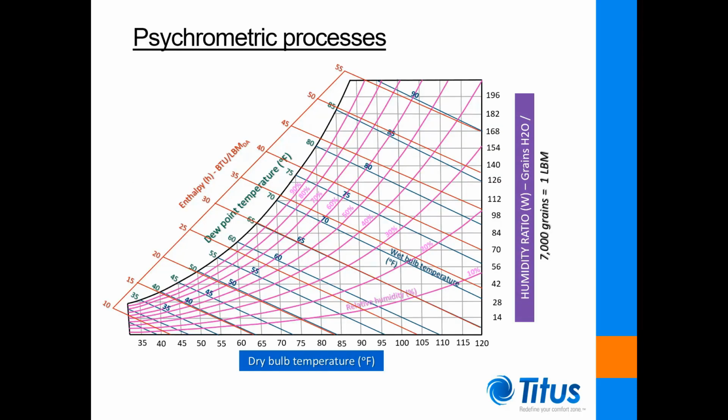Now let's examine some of the psychrometric processes which regularly occur in HVAC applications. The most basic HVAC processes are sensible heating and cooling. These processes add or remove heat from the air without affecting the mixture's absolute moisture content. For example, a sensible cooling process occurs when the air mixture's dry bulb temperature is reduced without reaching the saturation line, thus maintaining its moisture content constant.